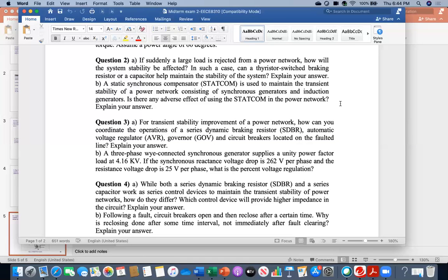I wrote STATCOM is generally used for reactive power control. The mentioned power network lacked active power control measures, since STATCOM could not control the active power. However, a governor is there in the synchronous generator for steady state speed control. So along with STATCOM, some breaking resistor or other active power control means should be implemented for transient stability.